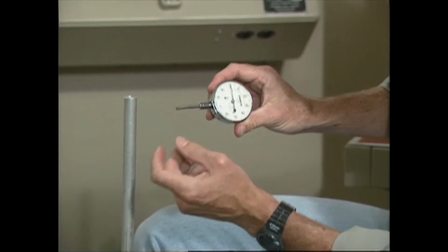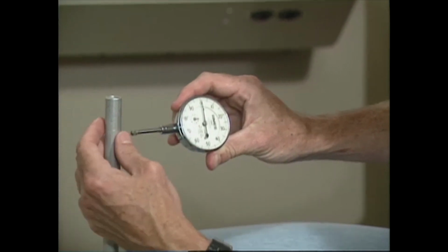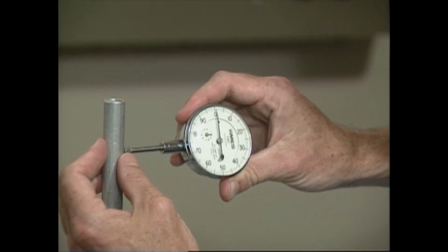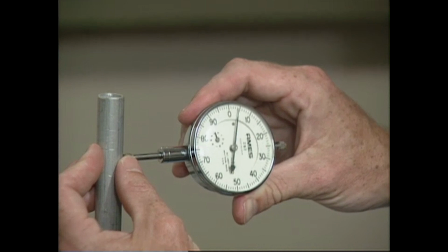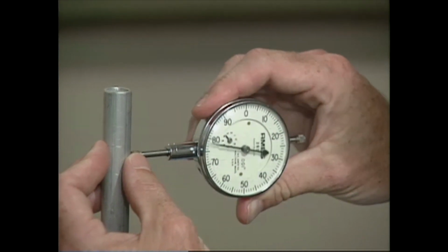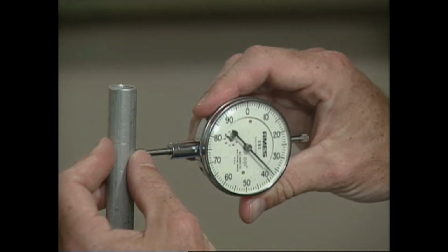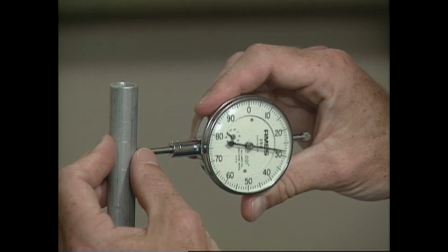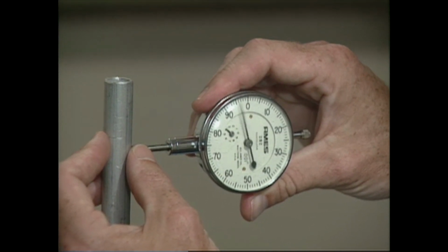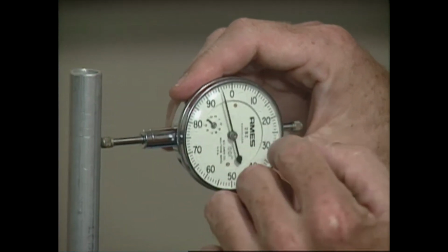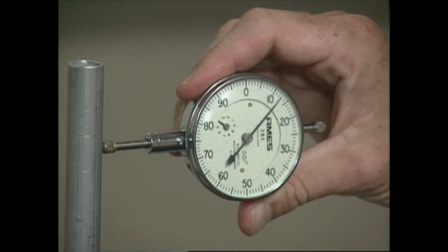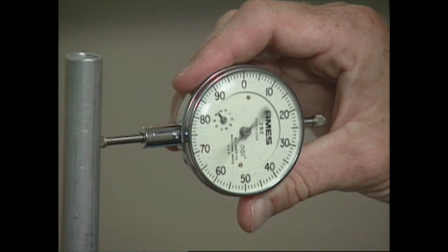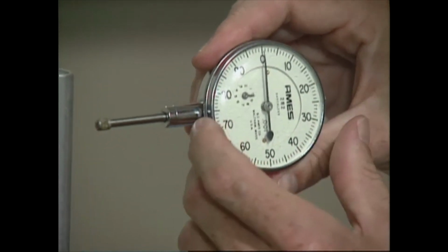Now, it's common for machinists to use something called a dial gauge here. Essentially what the dial gauge does is I have this plunger that pushes up against the object, and it will rotate the dial. So there's a very fine mechanism inside the gauge that will make a measurement of the position and show it on this needle here. And you can see that just my jiggling around here as I talk is causing the system to jump.